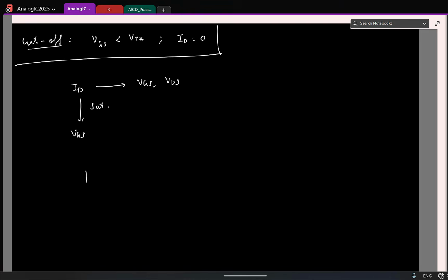So if I take a transistor and make sure that it is operating in saturation region, and for that let's say I put some voltage here, another some voltage here. Now this is operating in saturation, which means if I change the VDS, what can you say about the current? It will not change. So looks like I'm increasing the voltage, but the current is not changing. Which other circuit element behaves this way?